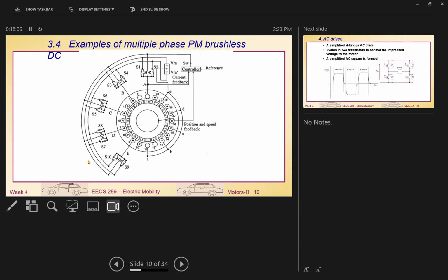Firstly, because of high power, each phase is only responsible for a portion of the power. For instance, of the total motor power, each phase only handles 1/3 of the power. In this case, we can share the power across each transistor. You can see in here, we are using many phases. Because the motor has so many phases, even if one phase is accidentally broken, the other phases still operate. It's just that in here we get more torque ripple.